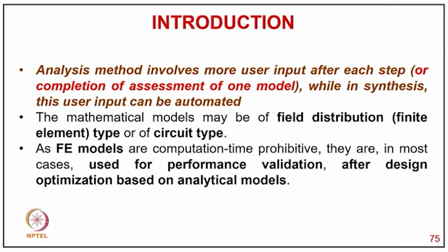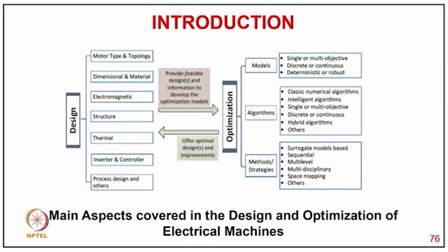The analysis method involves more user input after each step or completion of assessment of one model, while in synthesis this user input can be automated. The mathematical model may be a field distribution type like finite element analysis, or a circuit type. As FE models are computationally time prohibitive, they are in most cases used for performance validation after the design optimization based on analytical models. A typical example may be covered in the design and optimization of electrical machines.